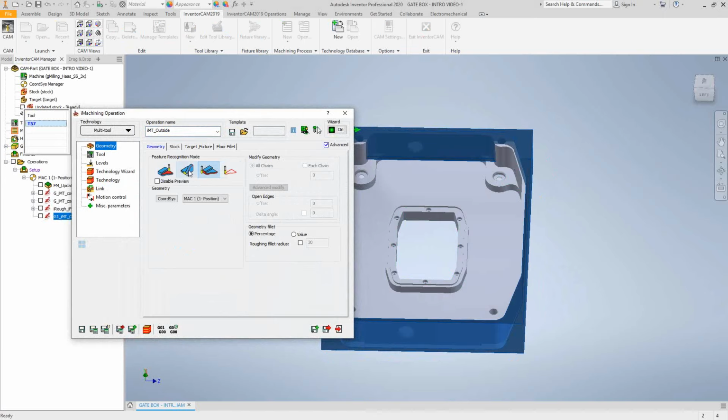How that's different from this chain selection is this one is automatically going to recognize all the nearby material. It'll extend your chain outwards. You can actually use open chains, and it'll extend the profile of the machining toolpath outwards. So it's a good way to allow the recognition to help you with open chains or sides, open pockets, anything like that.